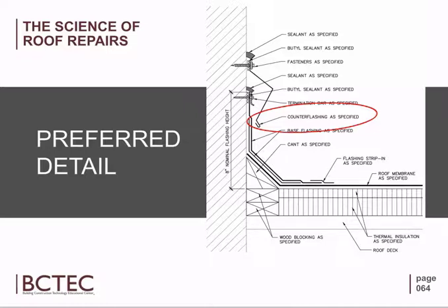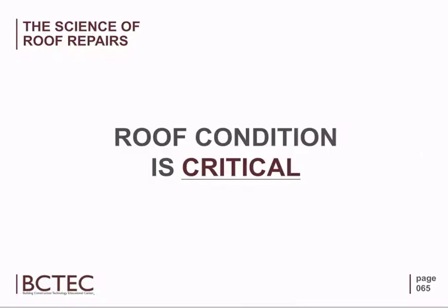Yep. So this is an example of a good, solid strategic repair. This is way over and above preventative maintenance. This is something that is going to be designed, we're going to catch problematic areas, and we're going to be strategic in the way that we approach them to really extend service life to these roofs. Because that roof we looked at, that's a 20, 30-year roof. That membrane can last a long time, but we've got 5 to 8 year details. That's not good. So we're going to really enhance those details and go about it very strategically to make sure that this is a good, solid roof system that achieves its expected service life.